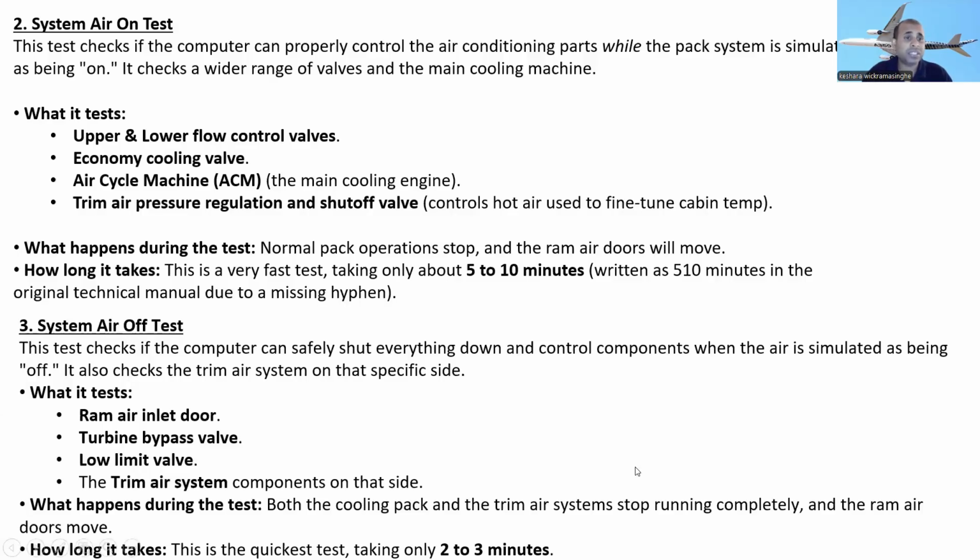So let's go to the next one, the system air off test. This test checks if the computer can safely shut down and control components when the air is simulated as being off. It also checks the trim air system on that specific side. Okay, remember, this test checks if the computer can safely shut everything down and control components when the air is simulated as being off. It also checks the trim air system on that specific side.